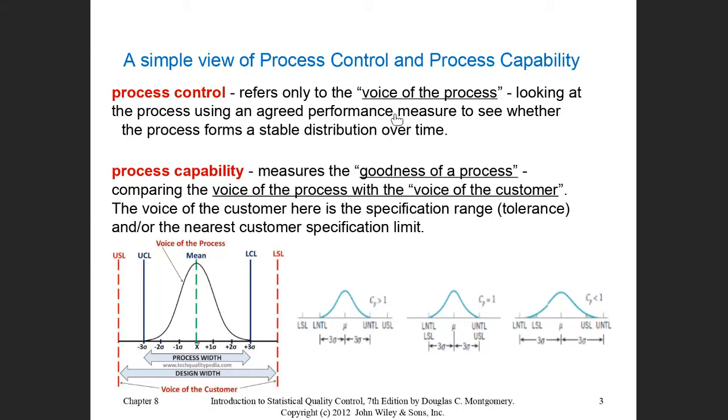So where do we need the process capability, and why do we need these inferences, and why do we need this explanation or identification in the process? We need them to make sure, before we start doing the control charts, whether our process is capable of meeting the specification. If it is not capable, then the control charts have no meaning at that time.